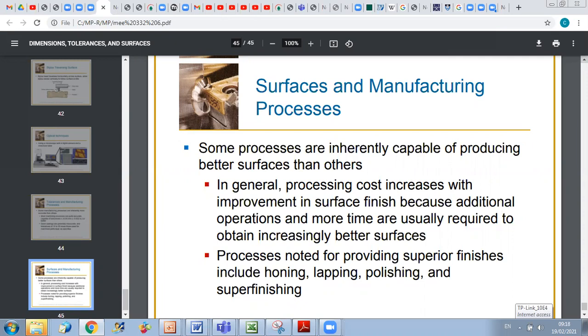Concerning super finishing, which is also known as micro machining or micro finishing, it is a metalworking process that improves the surface finish and workpiece geometry. This is achieved by removing just the thin amorphous surface layer left by the last process with an abrasive stone or tape. This layer is usually about 1 micron in magnitude. So super finishing is one of the most accurate processes that will give you a nearly perfectly smooth surface.